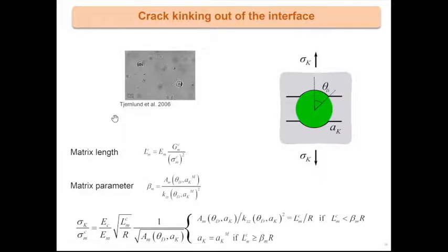And this is a little bit complicated, in fact, because if you know interfacial crack propagation, you cannot analyze this kind of situation, that is to say, the kink out of an interface, with the standard Griffith criterion, because in this case, you have some oscillations in the solutions, and you cannot define the standard energy release rate for this situation of kink.